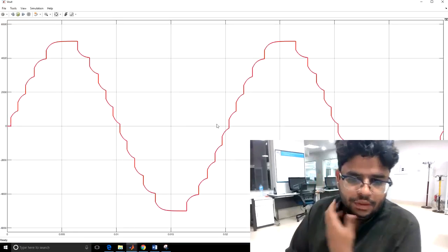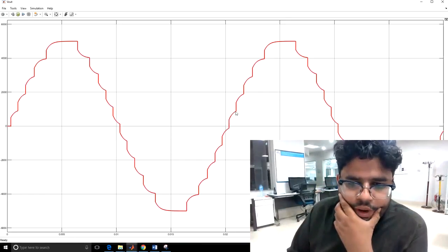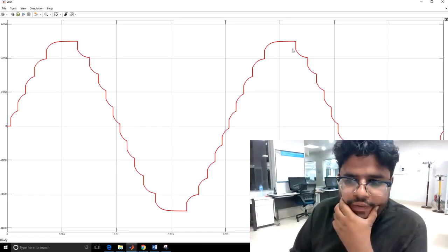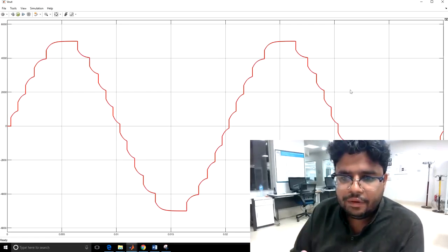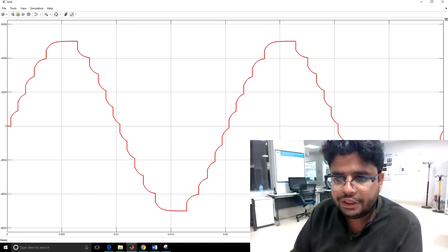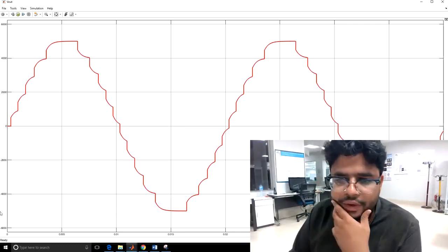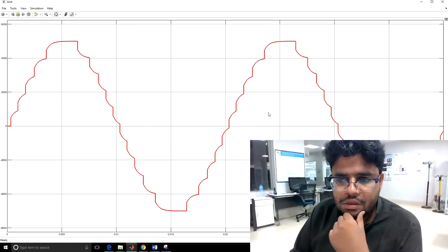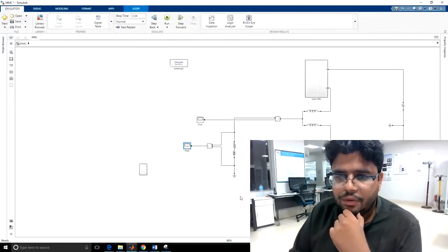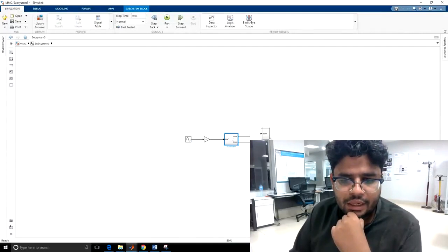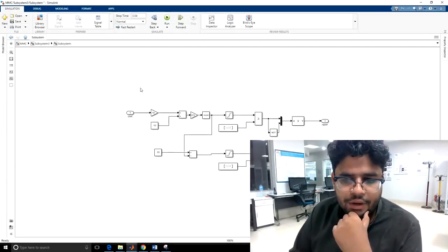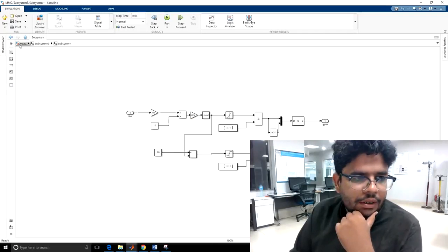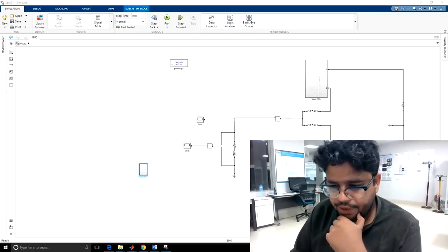Alright, perfect. So now we are getting 1, 2, 3, 4, 5 levels, 5 for the positive portion, 5 for the negative portion, 10 and 0 level. It means overall we are getting 11 levels with 10 half-bridge submodules. So this is an 11 level MMC with N plus 1 level conventional NLC. Next, we will discuss in detail how to design this NLC control portion, and the function of each block. Thank you very much for listening.